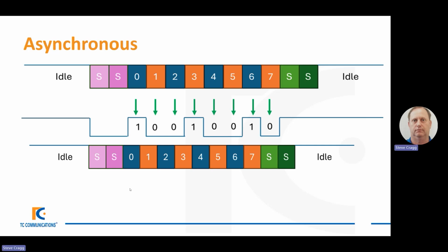and then when it's received, the receiving device thinks that the data should have been sent faster than it actually was. And you can see here that it's thinking that it would have received the data by the end of, not even the end of the first stop bit. So when it does its sampling in the middle here, it will take the first one, it will look, and you can see by the long green arrow that it actually looks at that as a 1. That's cool. That's what it was expecting.